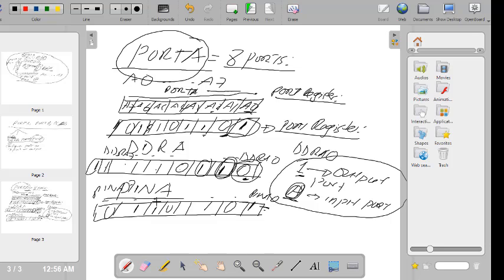But this one is read-only, meaning you can read only information from the pin register, but the pin register is a reflection of what is found in the port register. Very important that you understand. Now, how do we use it?